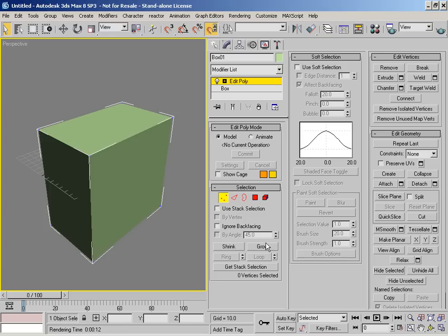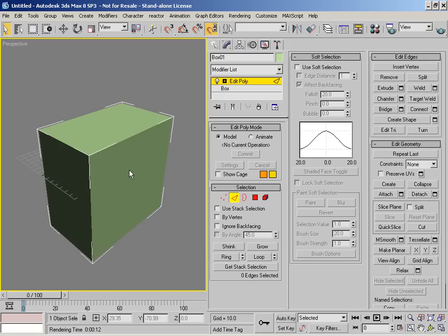Like, you know you're in the vertex subobject mode, you're in create, it creates a vertex, but the thing is it floats, so therefore you need to be able to join it together. Same deal with edges. You can basically create edges going from that vertex to that vertex. You can't do it from that vertex to that vertex because you're going through another edge.